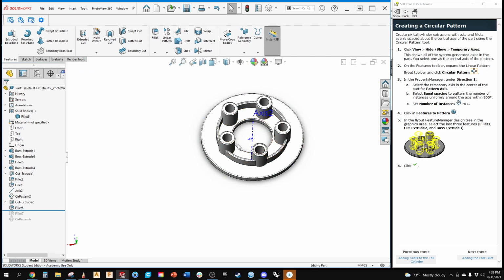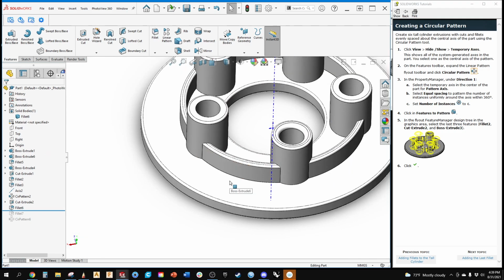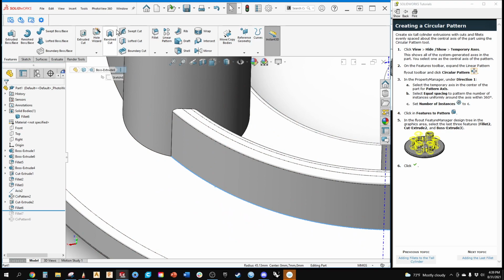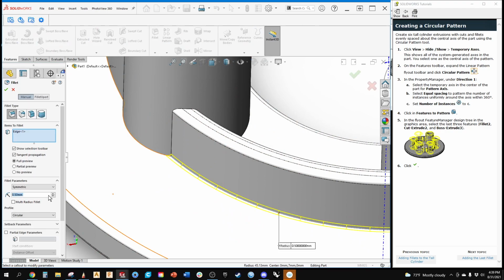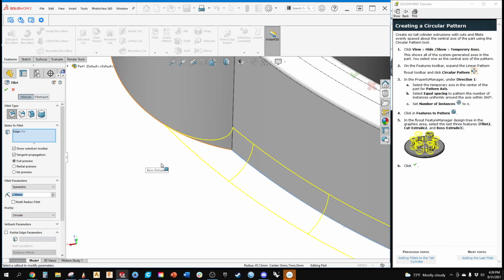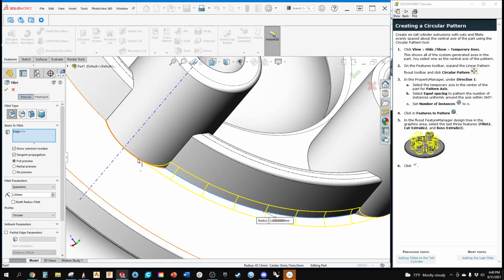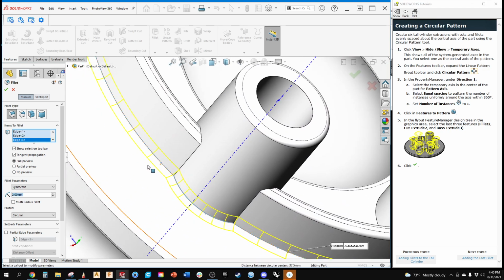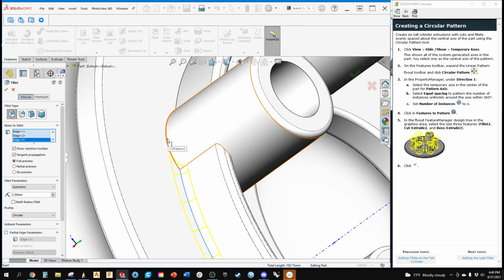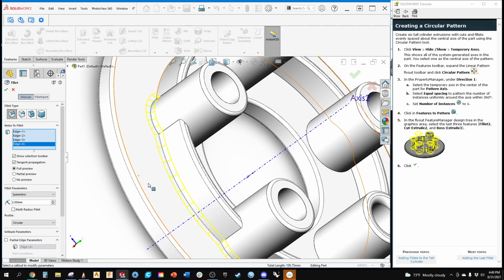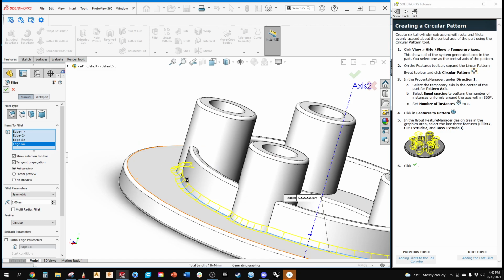It bothers me sometimes. So if I want to put a radius all the way around this area, and I click this edge, it stops right here because it can't wrap around a corner. There's no smooth direction for it. So if I do that, but I come and say, okay, well then I'm going to click that edge, I'm going to click that edge, I'm going to click that edge, and I can keep going, is a bit of a pain.